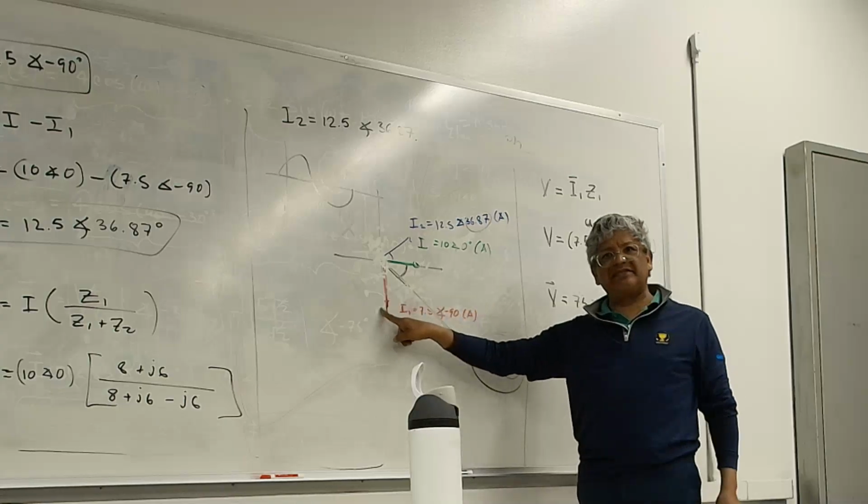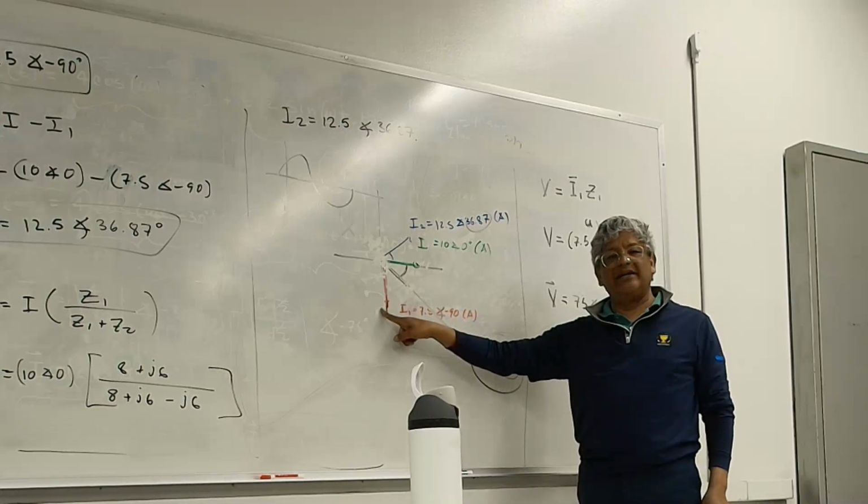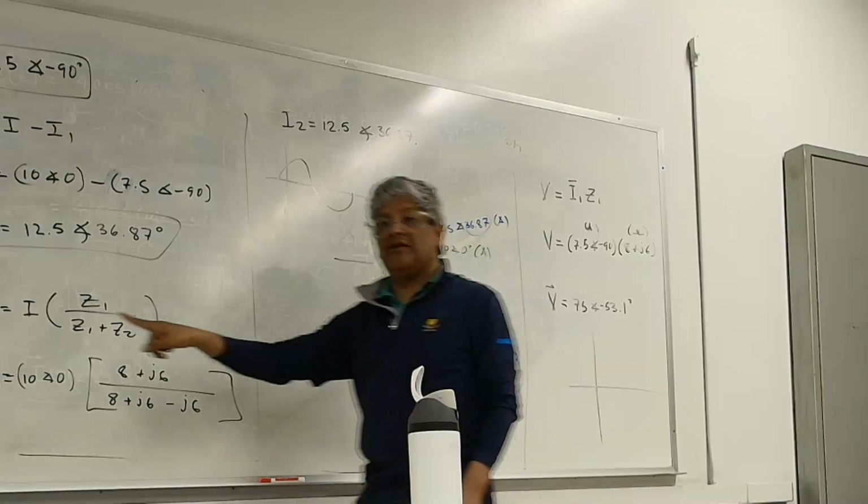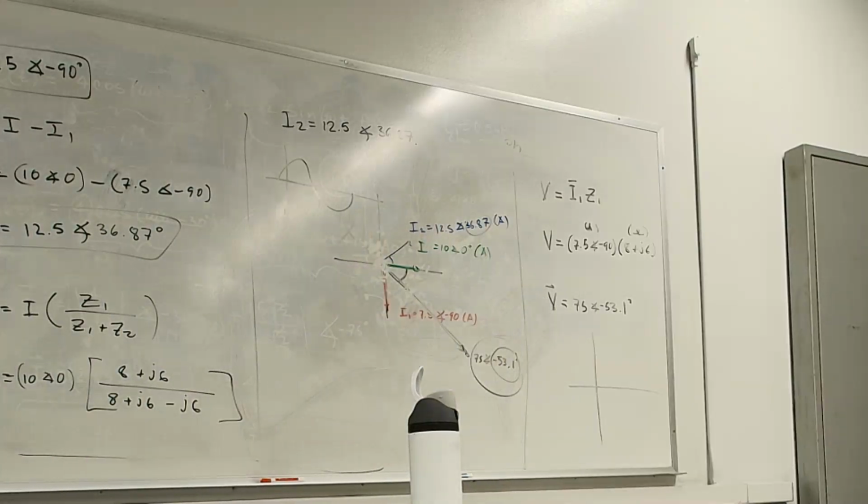This is behind. Does it make sense that this is behind? Yes. Why? Because it's at the load. It's an inductive resistive load. Is it 90 degrees in between them? No, because I have a resistance.